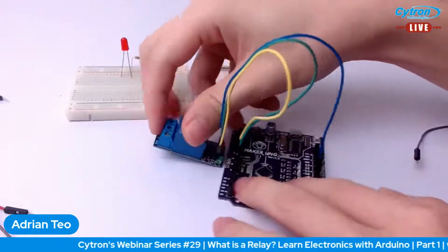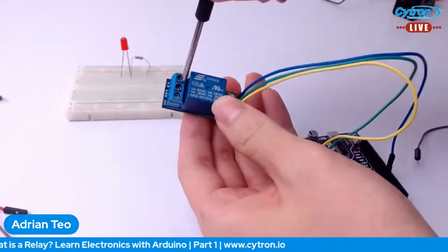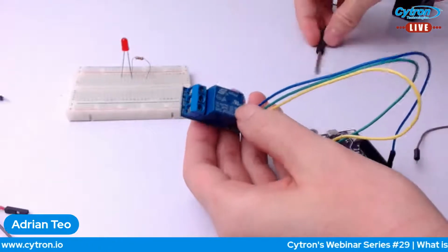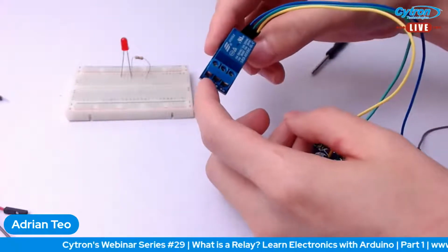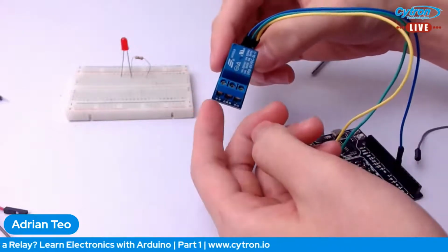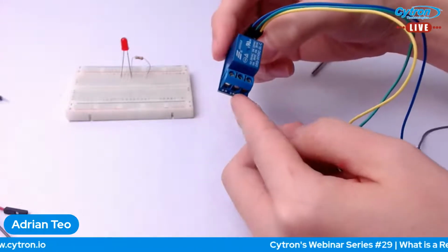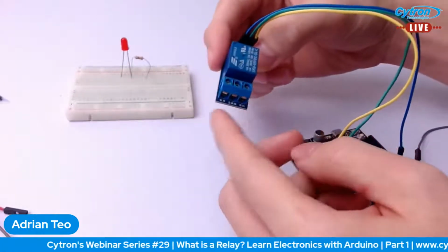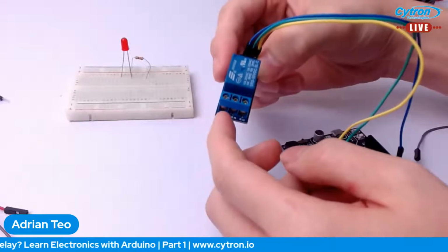Next, I will need to connect this side of the relay using a screwdriver. So these are the screw terminals. You have to remove the screws. If you bought your relay from China, there will be Chinese words over here. From left to right, I'm going to read it out in Chinese. It's called 常开, which means it's always open. At the center is the common terminal. But on the right side, 常闭 means it's always closed, and on the left side, it's always open.